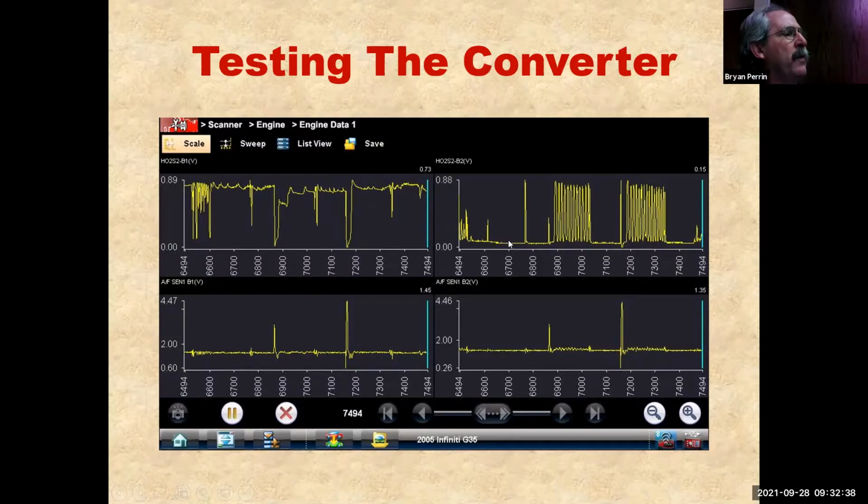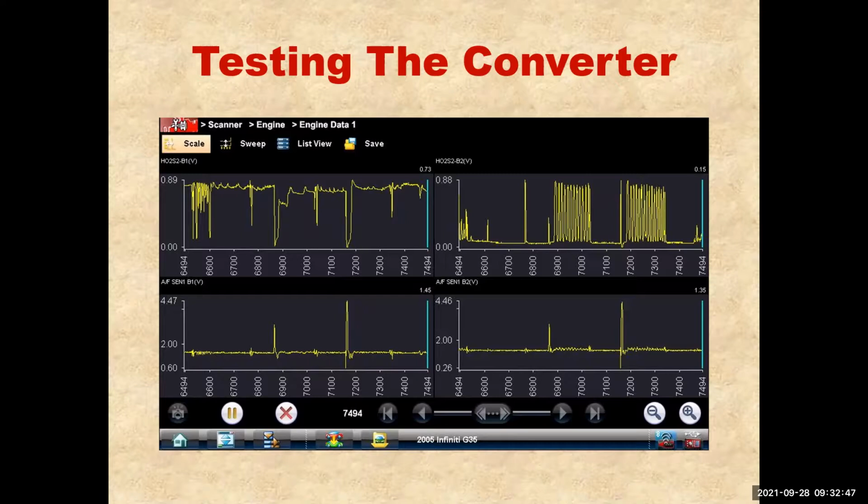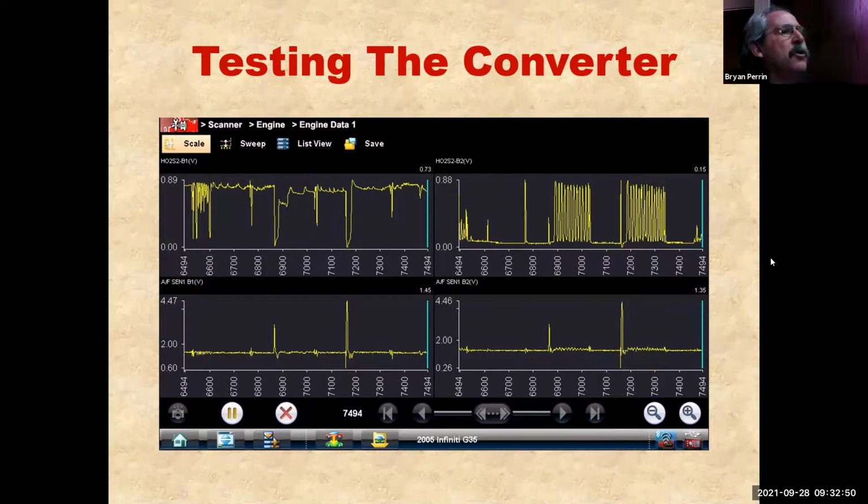Here, when I'm at idle, my rear sensor is low, which I would see on an early OBD2 vehicle or a car with a bad cat. And so the catalytic converter is what was causing the problem. It was interesting here because this is only available as a dealer. And my service advisor was really nervous because there was nothing saying the catalytic converter could cause this problem. There was nothing in the manual. There was nothing in Identifix. No one had ever put a catalytic converter on to fix this problem that had reported in Identifix.